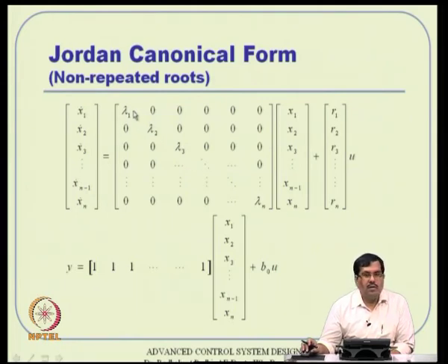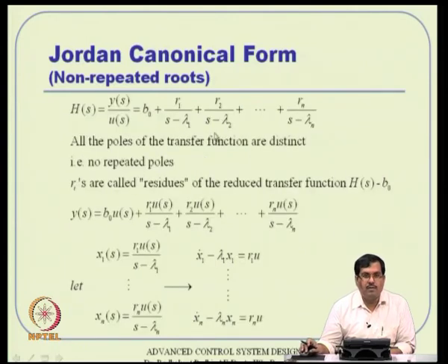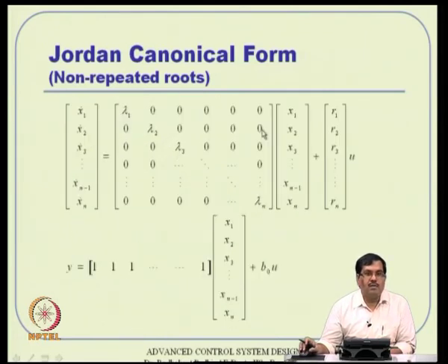Okay. And remember, for diagonal matrices, the eigenvalues are the diagonal elements directly. In general, if it is a triangular matrix, the eigenvalues are the diagonal elements, that you can see from the definition of eigenvalues actually. So, these elements, the roots of the denominator polynomial equated to 0, are nothing but the eigenvalues of this system matrix actually. Okay. And we will see later that the stability behavior of this system dynamics only depends on the eigenvalues actually. So, that is what happens later.